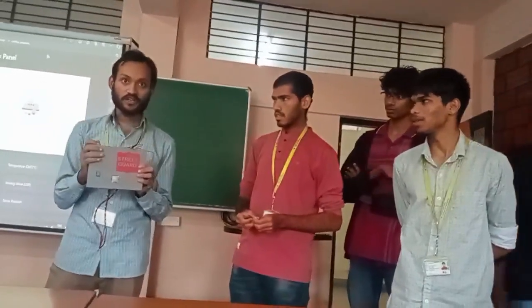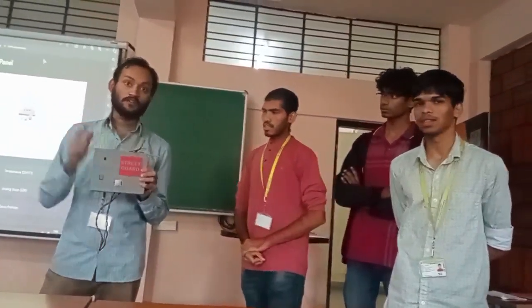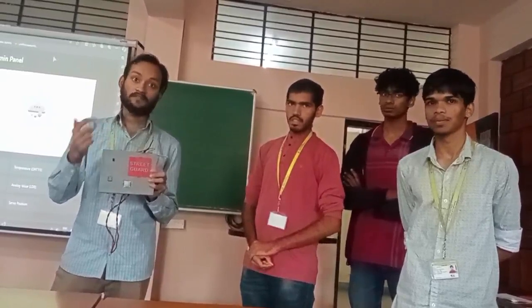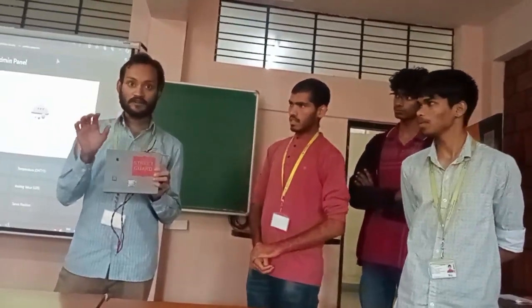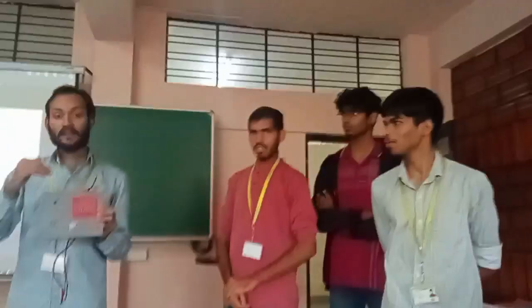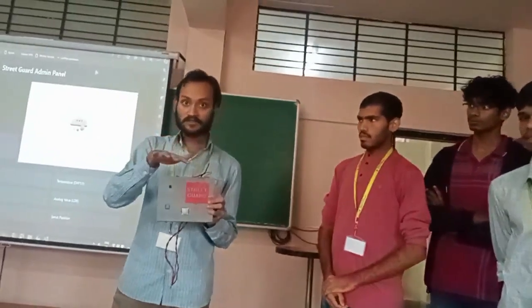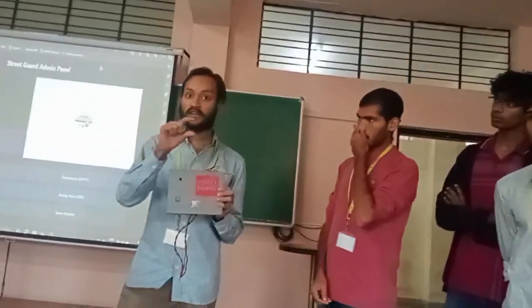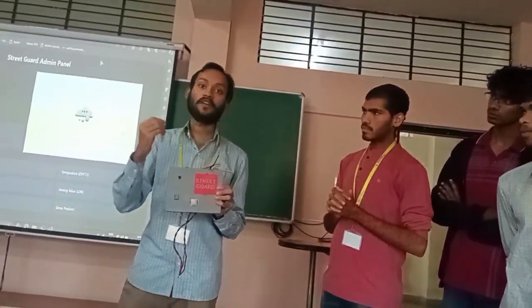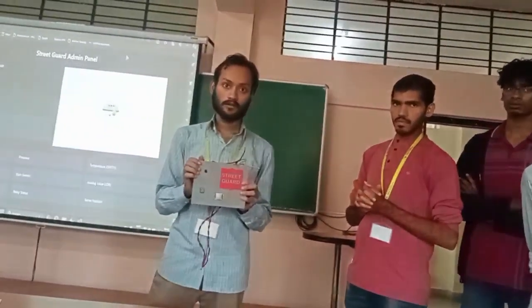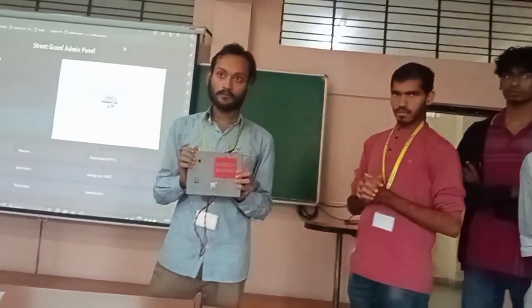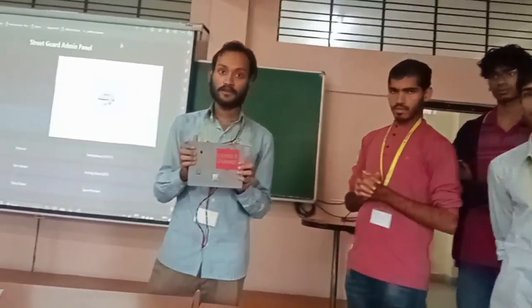Currently, how it is working: the ESP32 is connected with Wi-Fi. If it is connected with Wi-Fi, it will get its IP address. I am controlling everything with its IP address. I set up my own Flask server, and on this port I will forward the port. When I forward the port, I will get one URL. With that URL, you can control this from anywhere. No, the thing is you need some technology to access it, right?